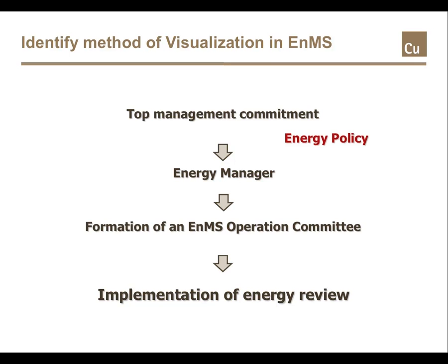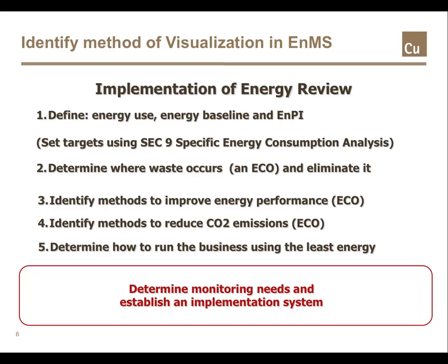Once you've appointed an energy manager, you should establish an operations committee to run the operation. The operations committee's first task should be to implement an energy review. And here's a summary of a typical energy review. You understand how the energy is used. You define an energy baseline, and you target energy performance indicators using SEC, specific energy consumption analysis.